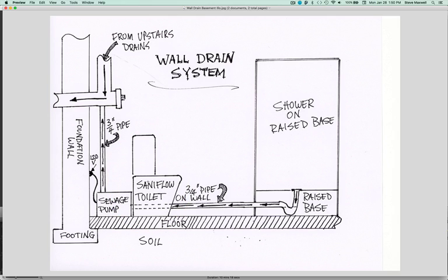Imagine a regular toilet. It's got water in it, and it's porcelain, and it's got a seat. But when you flush it, the wastewater doesn't go down through some large diameter pipe, like 3 or 4 inches in diameter. Instead, the sewage goes into another part of the unit, which is the sewage pump. In this case, the toilet also grinds things up. So it's not just going to pump it up and out into your main drain that's above the floor, but it's also going to grind it up. That's where the word macerating comes from.